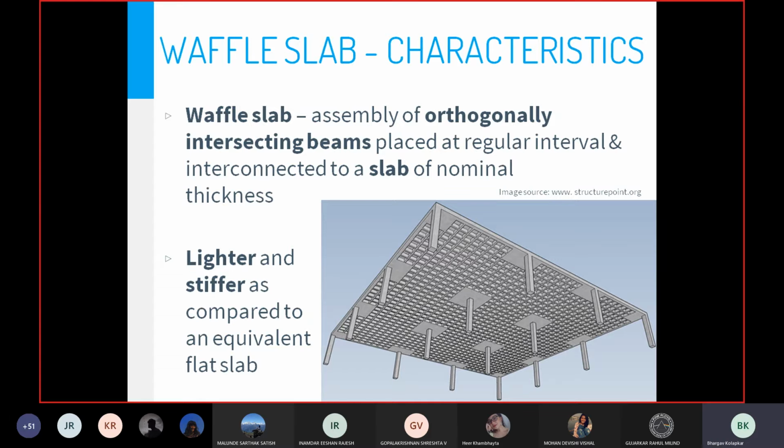We have looked at the example of how a plain steel plate has very less stiffness when you compare it with a steel patra. So in a steel patra, what you're doing is you are corrugating it, or you are stiffening the system. Similarly, here, you're bringing smaller beam sections, which are very close to each other in both the directions. So you're really stiffening it.